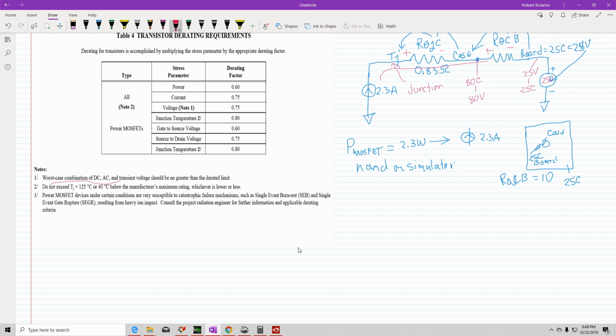Of course something will pop. You'll probably hit the current limit on your power supply, or something will burn up. So anyway, this is your proof that this is one of the ways that you can calculate your thermal junction, whether your transistor is getting hot or not. It's a very nice trick, a little simple model that you can use to simulate and check your designs.